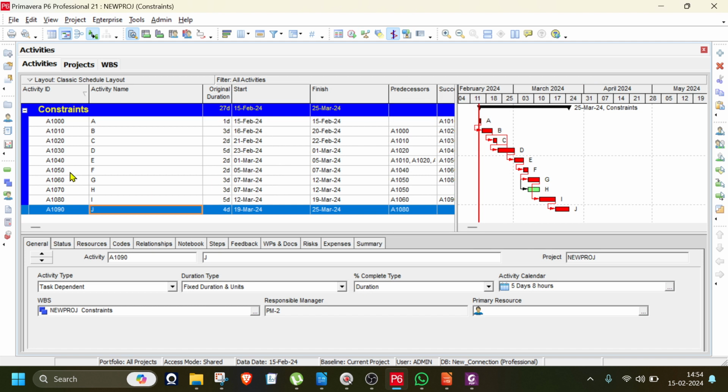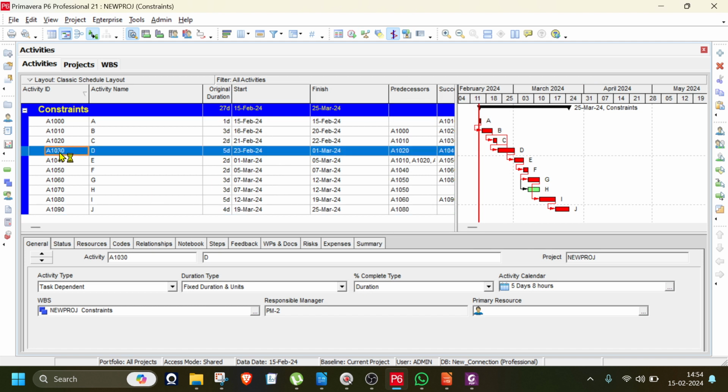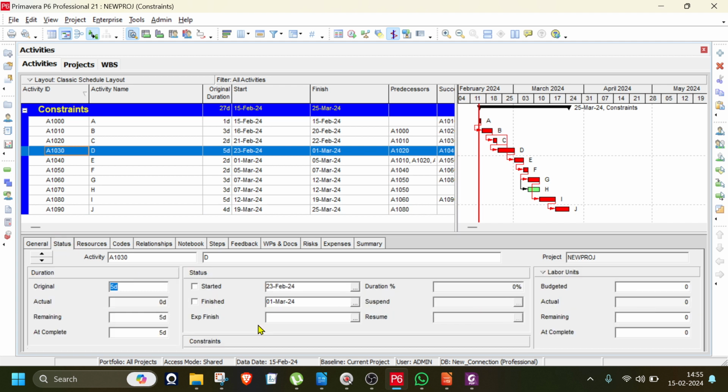Now here 23rd Feb, right? So just go here. I have to just click here and then go to the 26th, Monday. Okay, now schedule. See, this activity moved so much, extended to this so much. Start on or after. What does it mean? 27 days. Yeah, that didn't change because the activity remains 5 days.